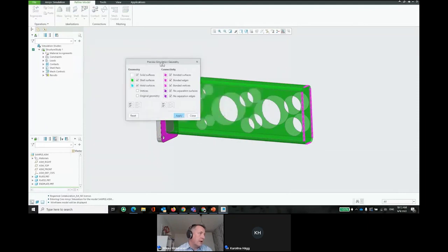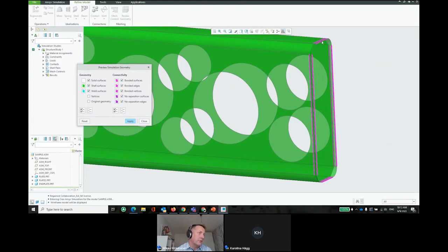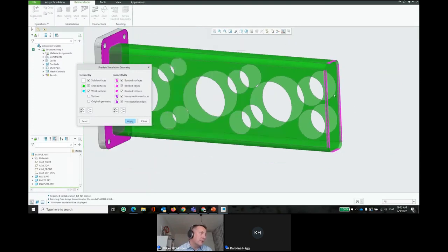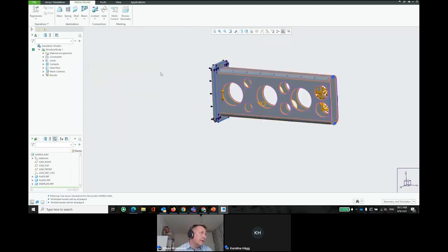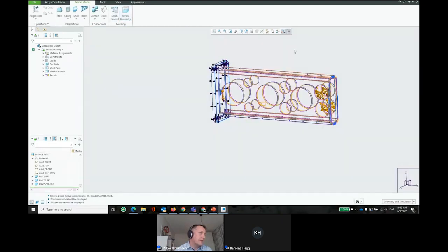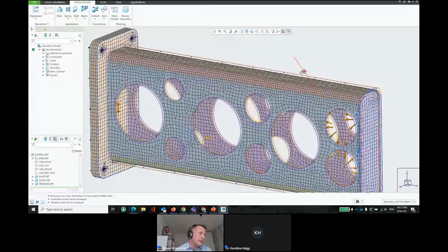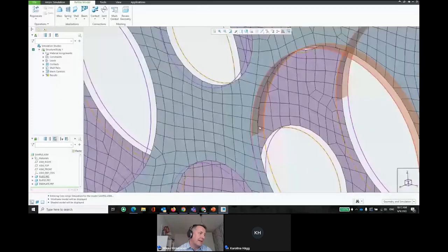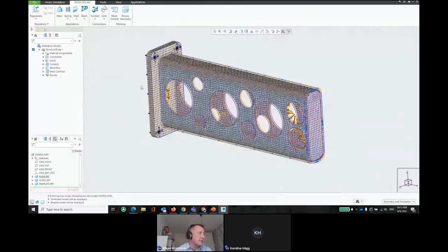Then, how do we connect these things together? As you can see, we have bonded surfaces and bonded edges highlighted in a cyan-magenta color here, also here. So basically what you can do is bond these elements together. Then, should you mesh this, you end up with the shell mesh. As you can see, there's no thickness here, even though the original geometry had it, because thickness is numerical in this one, but on the other hand, here we do have a volumetric thickness since this is solid elements.